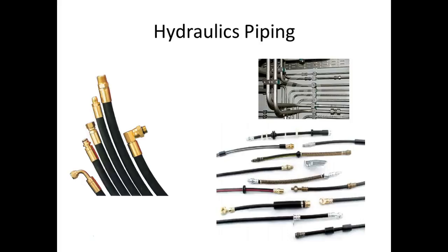Our hydraulics lab had quick disconnect fittings, and they were a lot like the fittings you get for your compressor. Most people who have a compressor have that quick disconnect on them. The problem that we had is we had to do that because we were in a lab environment and we had to hook up different circuits. You did your piping with those quick disconnects. Well, what would happen every time you pop one of those quick disconnects open, even though it had a check valve on it, it still had pressure.